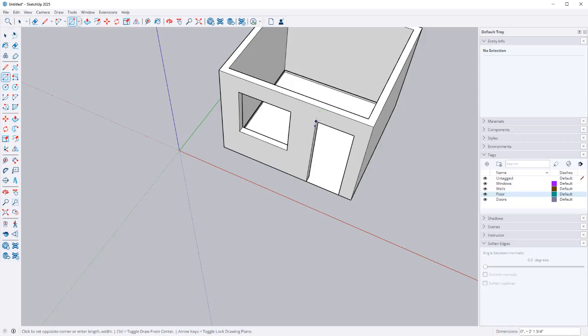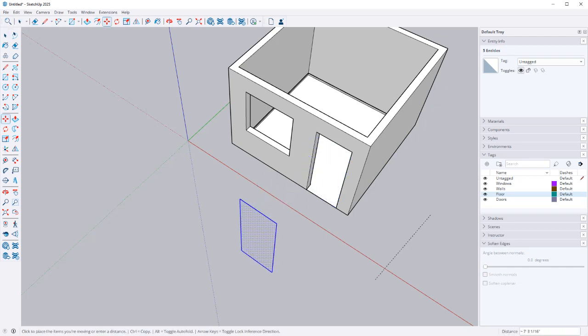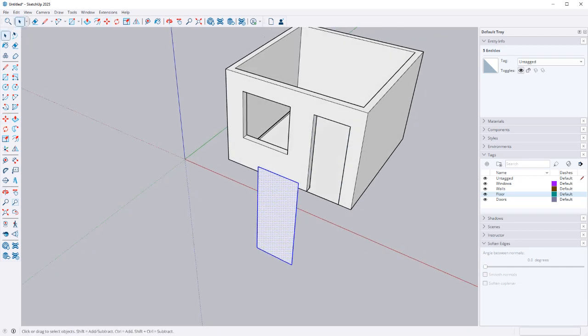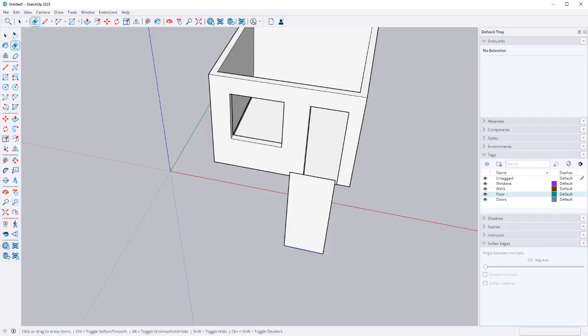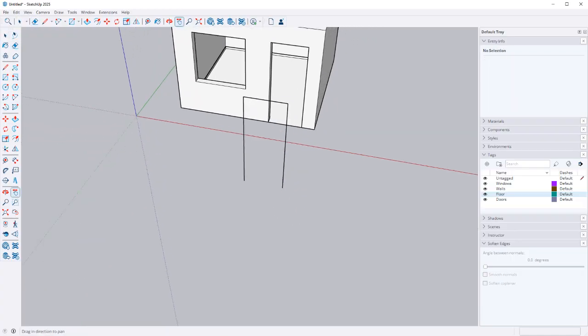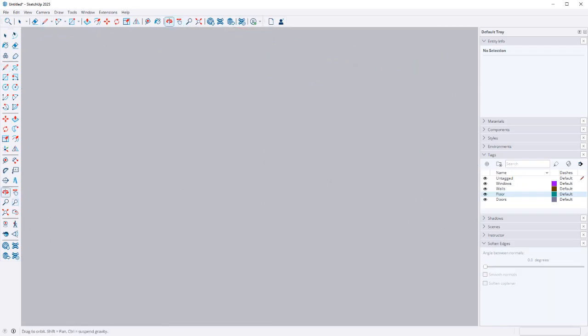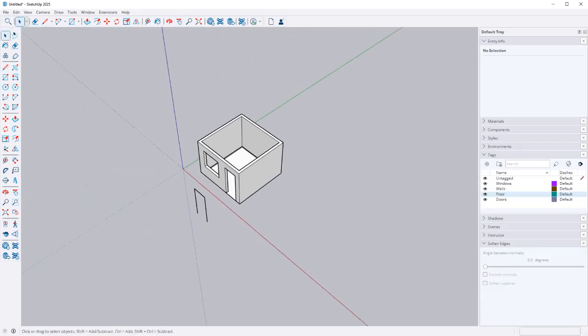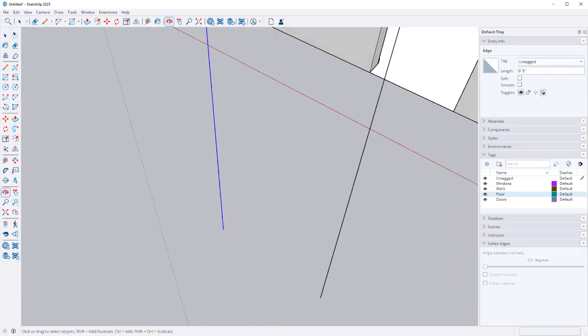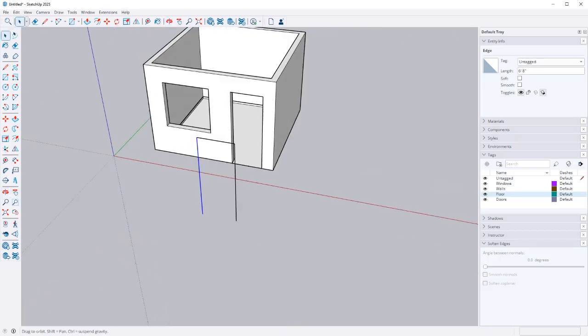Here's how I build doors. Feel free to come up with your own. But now that this is grouped, I can draw this directly on top of it. Okay, so I've drawn that in there, and now I'm using this as a reference. So I've got this door area right here. To get rid of the interior here, I can just erase this bottom line right here, and that gives me this pattern that I can trace to create a door. I use 6-inch interior walls. If you have something selected, it'll usually use that to try and rotate around.